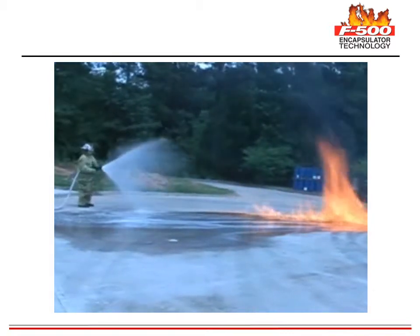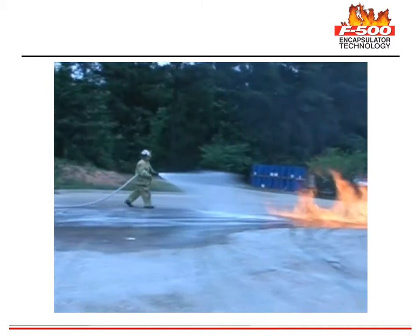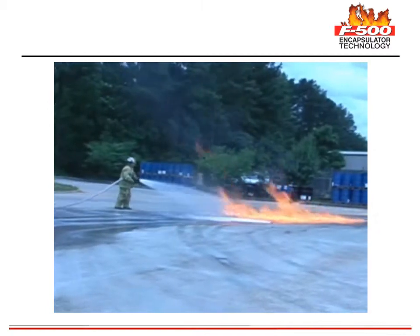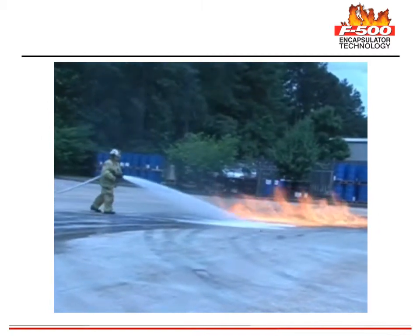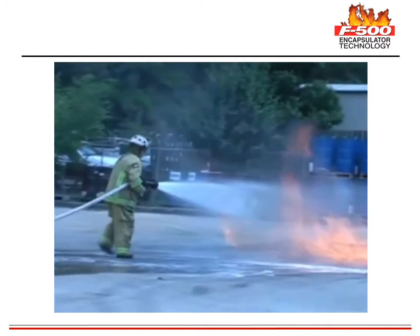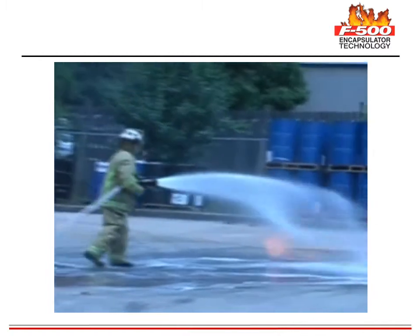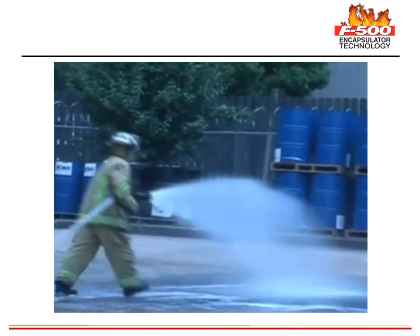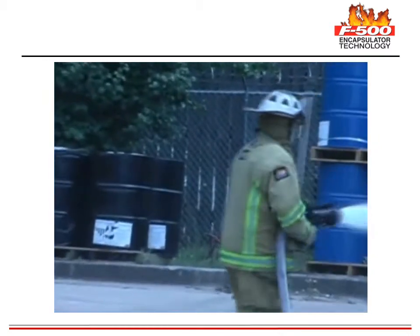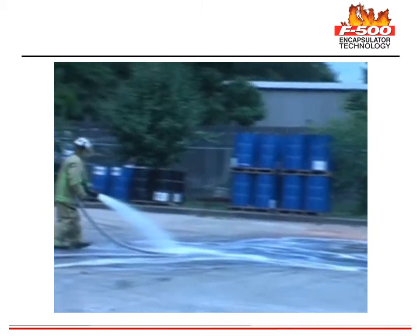Here, the firefighter spreads out 5 gallons of the E85, covering about 500 square feet. The untreated half ignites. The treated portion has been rendered non-flammable. The F500 mixture quickly extinguishes the remaining fire, making the entire 5 gallons of E85 non-flammable. The residue will evaporate and runoff is very limited compared to an NFPA 11 foam application previously discussed.